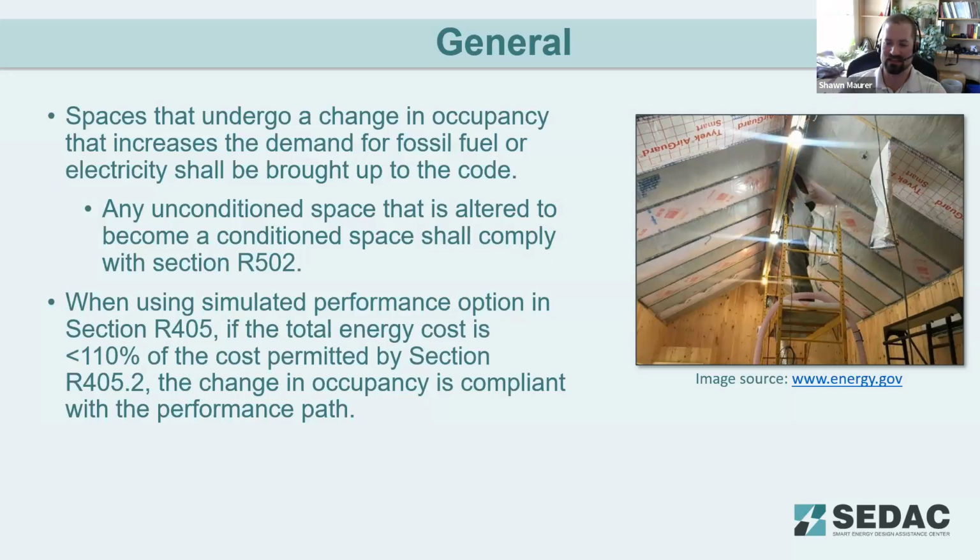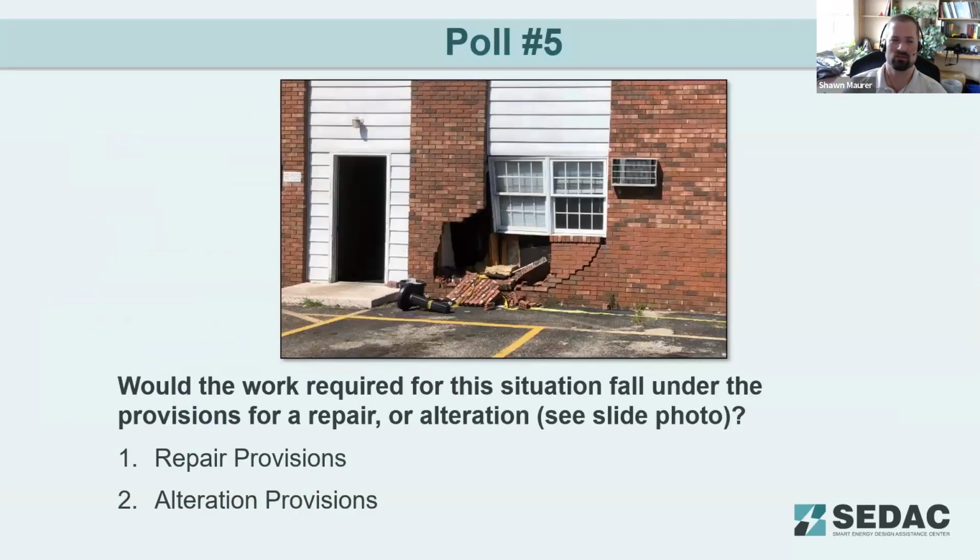So the existing building gets modeled to the energy code new construction standards, and then you do your performance model, which is what you're actually building. That's got that 10% buffer. It can do 10% worse than that reference design and be in compliance with the code still. So there's that little bit of exception, gives you some wiggle room.